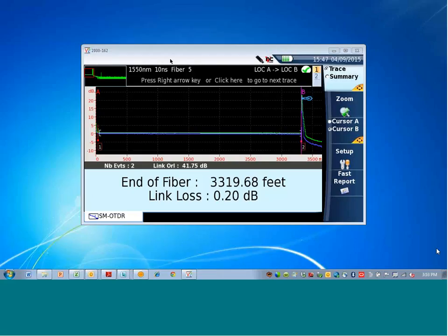Ensure the OTDR, fiber jumper and launch cable, and fiber under test are all clean and have been inspected. There is a different recorded session on using the P5000i fiber inspection scope to inspect all of the fibers.